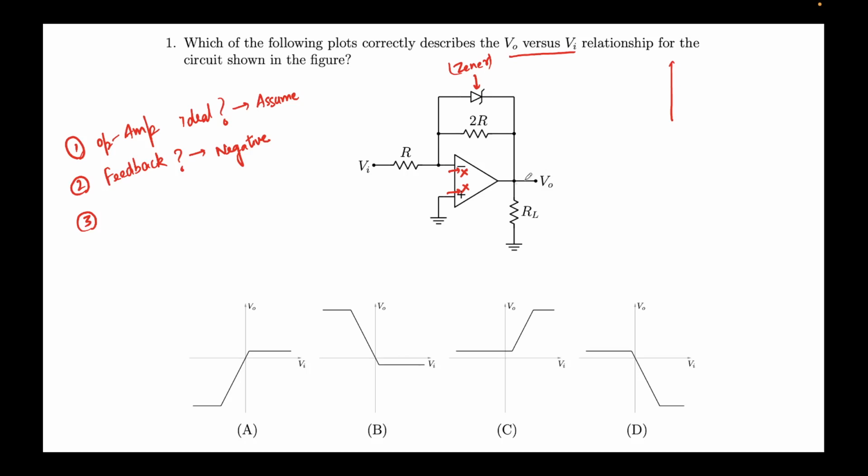So whatever V_out that we'll get will simply be the gain times the difference between these two. But there's a feedback also, so we'll have to solve this circuit accordingly. And you can see that this circuit is an inverting amplifier, right? Because the input is being fed to the inverting terminal. And the third condition, since no current can be flowing here and it's a negative feedback, is the condition of virtual short.